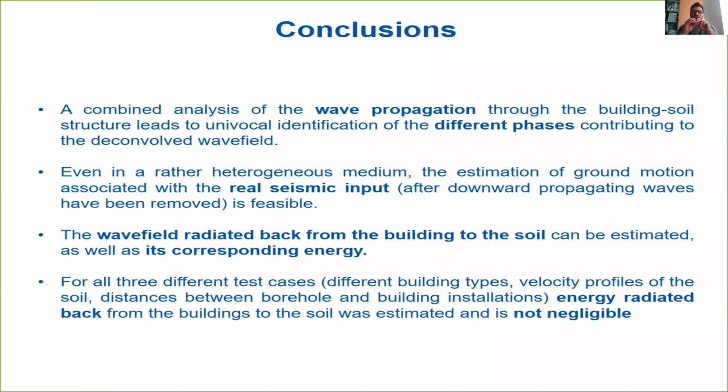So in conclusion, we have made a combined analysis of wave propagation for the building and soil structure, and we can identify different phases that can be related to the deconvolved wave field. We are able to evaluate the real seismic input, cleaning the input from the downgoing wave effect. But by the way, it's also important if we want to make a dynamic analysis of a structure.